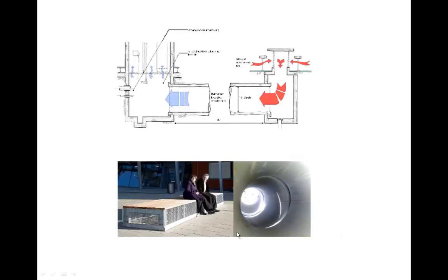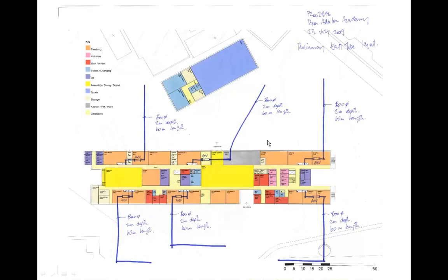And you have an inlet, which on this job was disguised as a seat. So the air comes in through that inlet. It's pulled through the earth tube with a very low-powered electric fan, and then it pulls it into the building. That was our engineer's layout of the earth tubes.